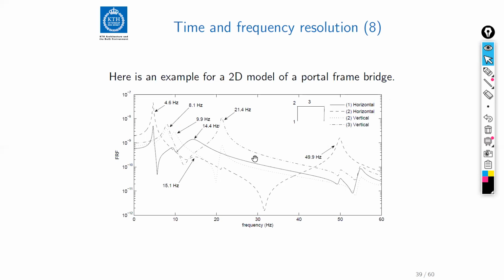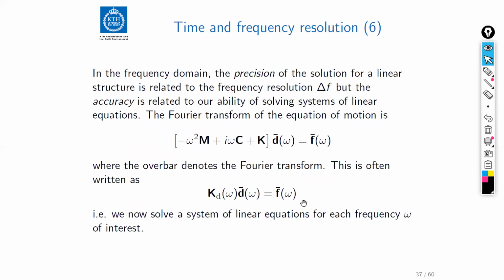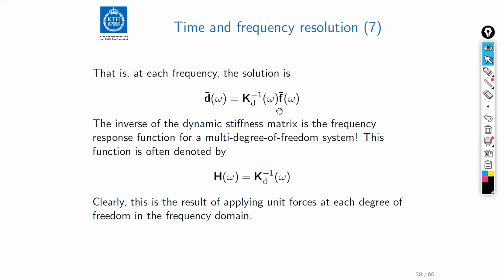So solving the frequency response function gives us the same information, a little bit more accurate if we include the damping, as the eigenfrequency problem. But at the same time, it gives us the characterization of the system as a continuous function of frequency. So if we can just describe the modeling also in the frequency domain, then if we look at this equation here, if we can describe the force in the frequency domain, all we need to do is to multiply the force with the frequency response function. And then we will have the solution in the frequency domain here.